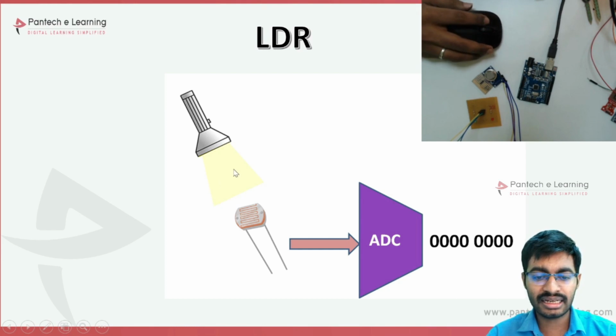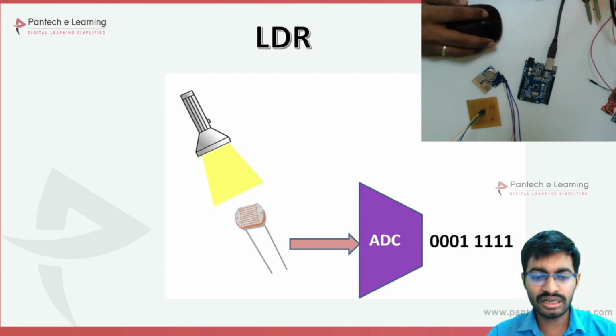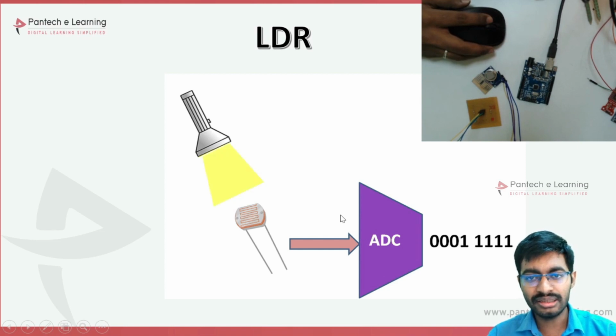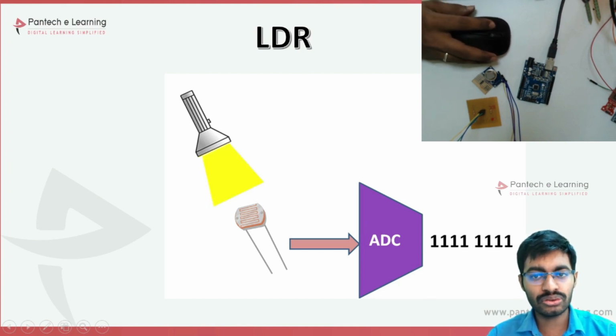Based on the light, the resistance will be changed. So here this particular light is considered as analog input. From that analog input, we will be using our ADC, which converts the resistance value from analog to digital, and therefore we will be able to get an output, and the variation will be from 0 to 1023.